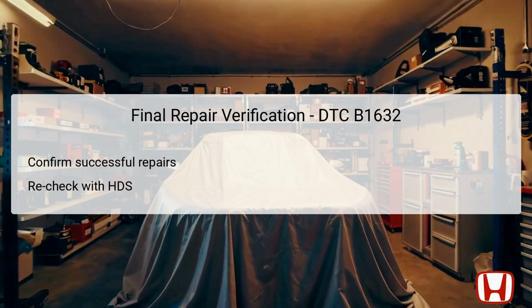Upon completing the necessary repairs indicated through DTC B1632 troubleshooting, it is crucial to conduct a final verification. This involves using the Honda Diagnostic System, HDS, again to check that the previously indicated DTC is no longer present, confirming that all faulty components have been adequately replaced or repaired. Testing the keyless access functionality post-repairs will ensure that the system operates as intended. Only by running these checks can you ascertain that the issues have indeed been resolved, thus safeguarding the reliability of the vehicle moving forward.